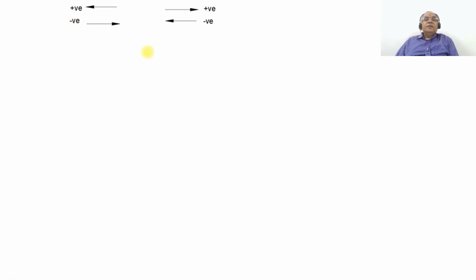And similarly, on the right hand side, the load which is acting toward the right side is tensile, which is positive. The load which is acting toward the left side is negative. So here how many forces are acting? One to the left side is 50, to the right side is 80, to the left side is 20. So by sign convention, 50 plus 20 is 70 minus 80, which is going to give you minus 10